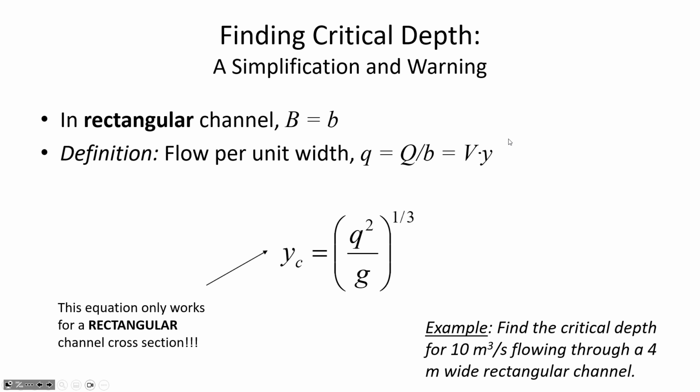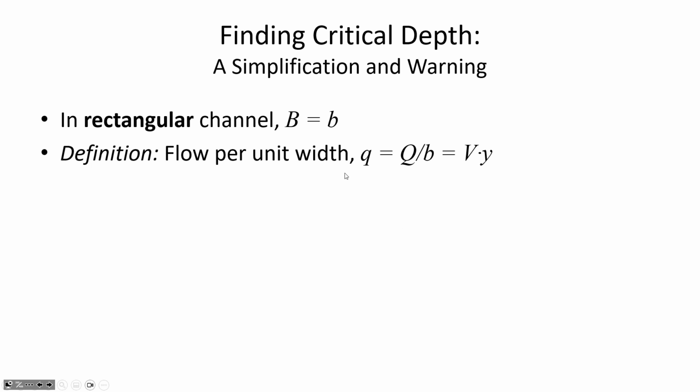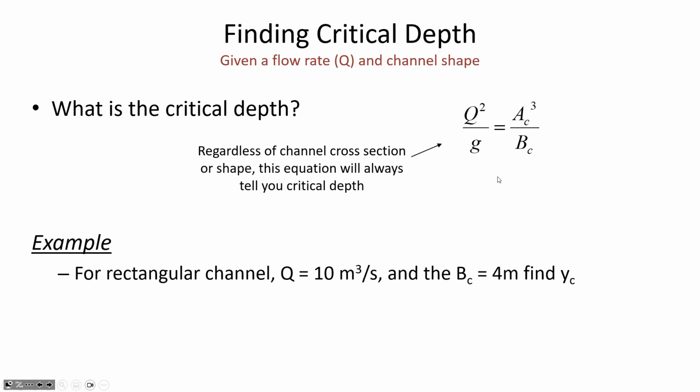So that's how you can find the critical depth if you've got a rectangular channel or if you've got any shape at all. You can use either of those approaches. This one only applies for rectangular. This formula applies regardless of the shape.